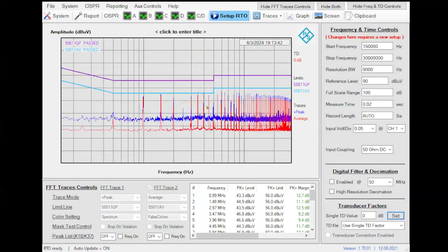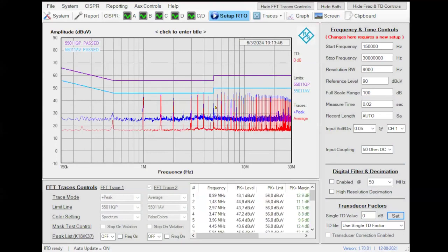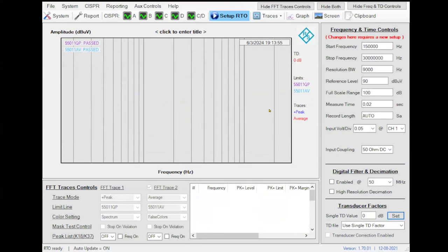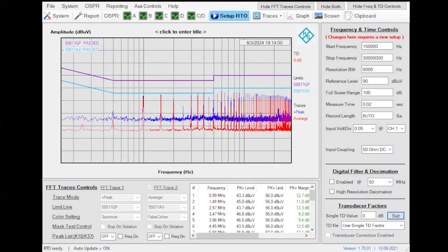This is without the capacitors touching the metal plate. Now I am going to touch. Okay, so you can see now, I am really below the limit. And it's a very useful technique to identify if you need to change or add components in common mode or in differential mode, to check if something is well connected or badly connected.